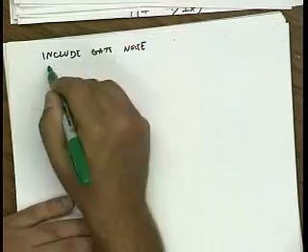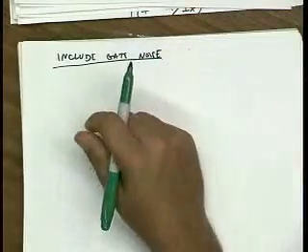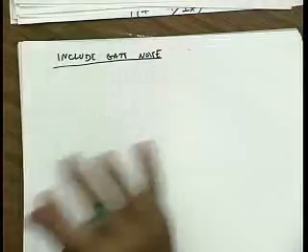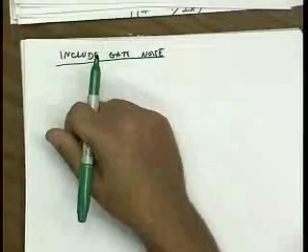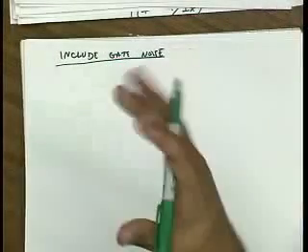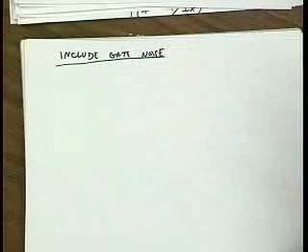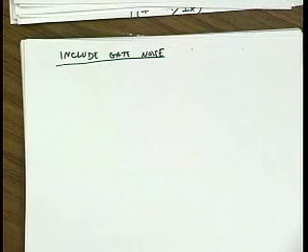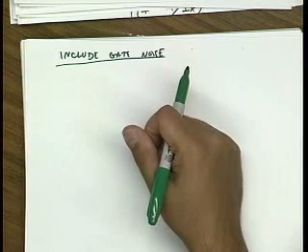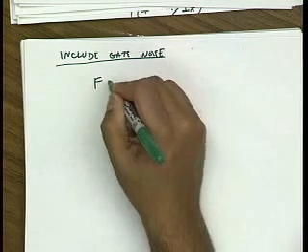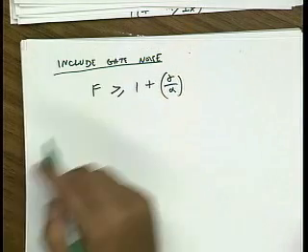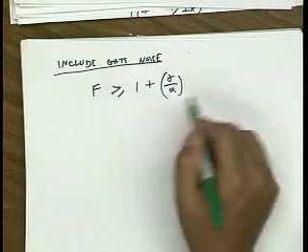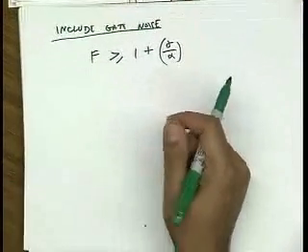The nice thing about noise calculations is that you can always start off really modest. Neglect all the noises except the ones you think are important, and then incrementally add noise sources. Because of superposition, it's pretty easy to do that. You just add another noise source, add a new term to your output noise voltage, and you get an incremental noise figure increase due to that. So remember, in lecture we derived that the noise figure was at least 1 plus gamma over alpha under the matched case, and we put the greater than because there are other noise sources that we've neglected. So what about gate noise?